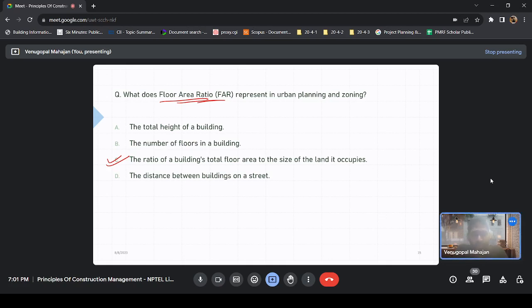Okay, so the town planning department, the municipality, divided your town into multiple areas, and for each area they gave different FAR, different FSI, right? Yes, sir. Why so? Why does it matter that in one area you can't have more than 3 floors, and in another you can have high-rise buildings, 10, 12 floors? It depends on the surroundings. Suppose the airport is close by, they will not allow you to construct more than a certain height. Okay, so that gives you the restriction on height, but it is not related to urban planning, right?